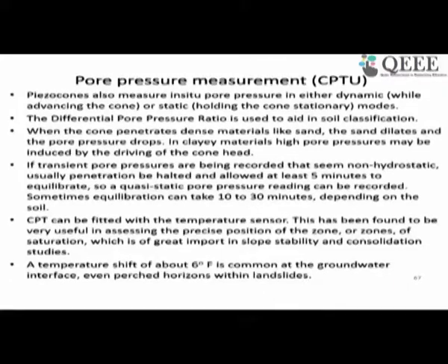When the cone penetrates dense material like sand, the sand dilates and pore pressure drops. When dense sand tries to dilate, the pore pressure will drop. In clay material, on the other hand, the pore pressure may rise with the penetration.